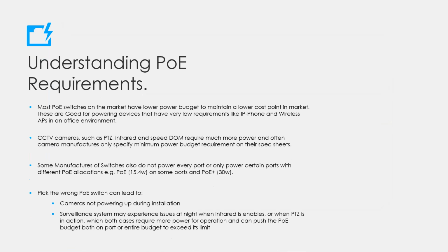Okay, so understanding the requirements on PoE. Well, usually OEM style PoE switches have a fairly low amount of PoE budget available, which might be okay for devices that consume quite less power, like IP phones or wireless access points where there are not many clients around.